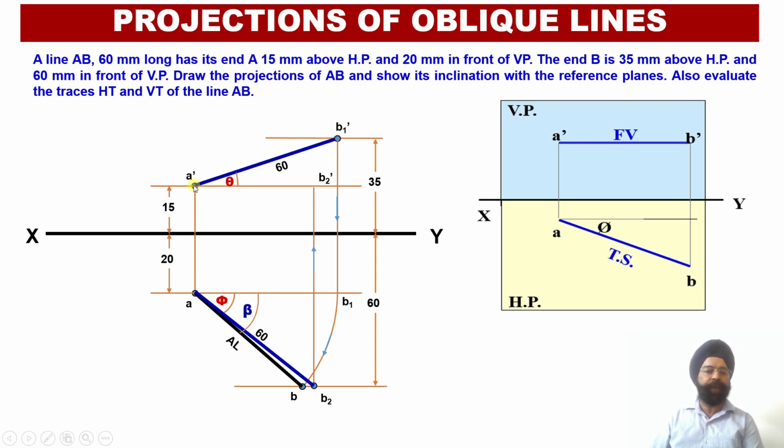So starting from here, this is my needle point, this is my pencil point. I'll draw an arc. Again, I have marked an arrow over here, that is I am going to move from this direction to this direction, and this arc has to be extended till it intersects with the horizontal locus line corresponding to the point B1 dash over here.